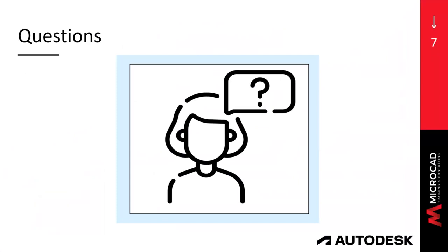I like that question because I touched on that, and there I'm going to expand a little bit. Go to reputable places. There is one place on the web called BIM Object. You can download Revit families for free. It has a whole bunch of families, and they do a little bit of weeding out of the families they have. There is a very old website from a long time ago called Revit City. You can get families there. Everybody uploads families into Revit City, so you really need to be able to weed the good from the bad.